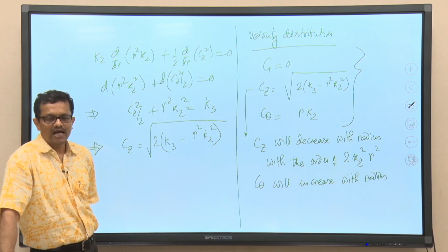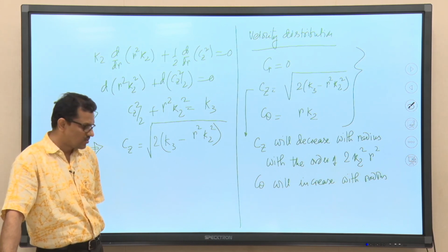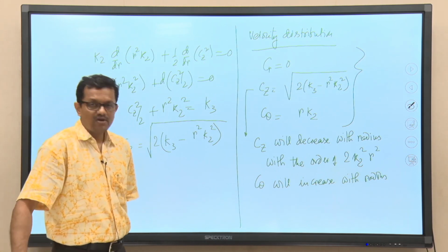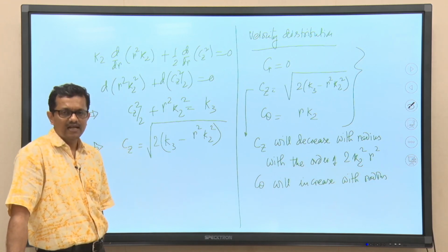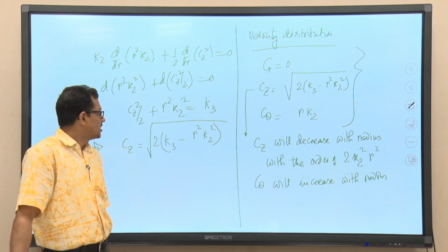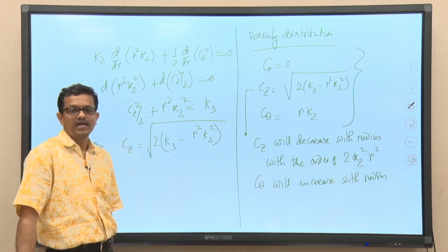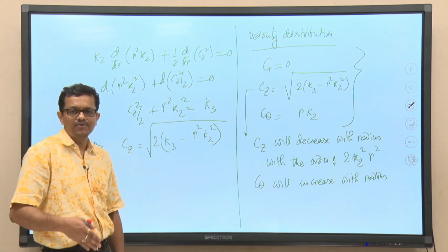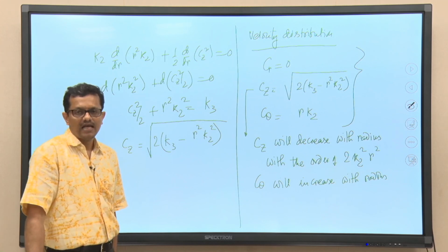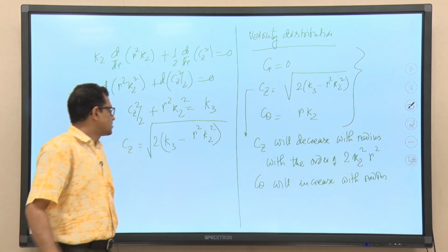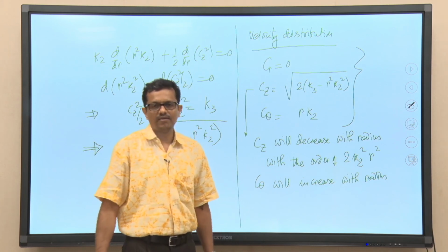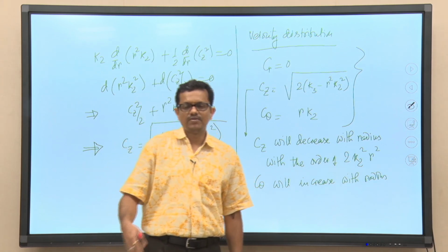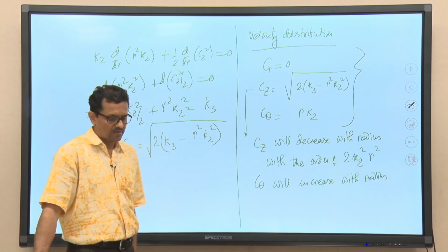When I discuss the degree of reaction for the axial flow pump, I will show how, if we know C theta and C z, we can calculate the degree of reaction. If we need to go for staging of the axial flow pump, then the distribution of flow velocities, pressure, flow angle and blade angle, information about these quantities will be very much required.